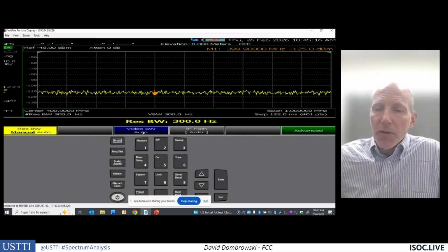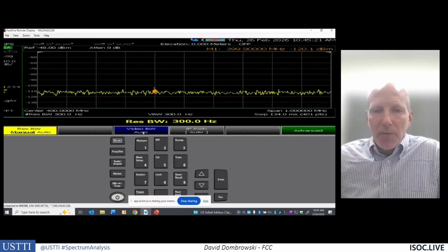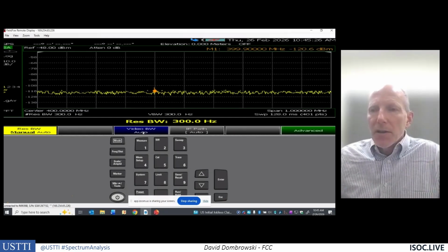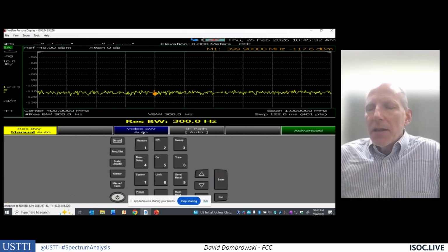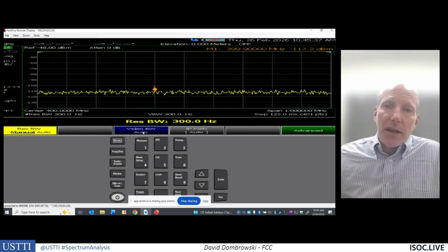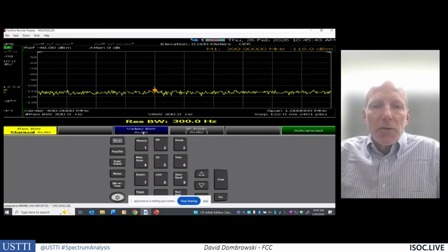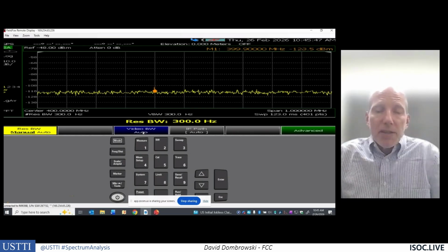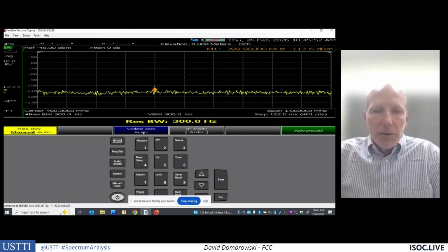You can improve that again with gains, better antennas that are directional, and with amplifiers and filters, and improve the sensitivity of the analyzer. So we increase that signal. You could put maybe a 20 dB or a 30 dB amplifier in line with the high gain antenna. Directional antennas give you another 10 dB. And so we could probably greatly improve that reception. So those are some of the techniques to pick out the weaker signals, right? Then we'd go further away and pick that weak signal up if we use amplifiers, high gain antennas, and filters.